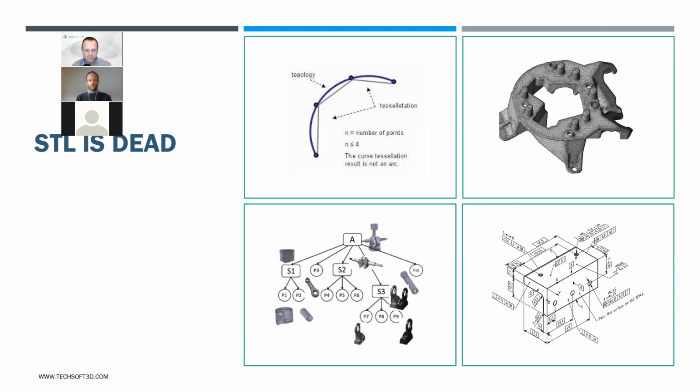So a couple of reasons. First of all, STL is a polygon, tessellated, primarily triangle file format. So it's just a group of triangles. Depending on how that set of triangles is created from the original CAD surface, those CAD surfaces, they aren't most times a set of triangles. It's a set of surfaces that are described mathematically. Your holes and your rounded surfaces are round. There's cylinders, and they're tori, and they're cones.